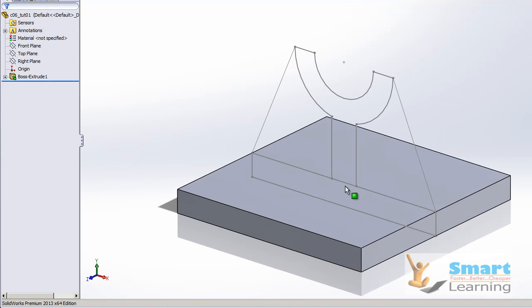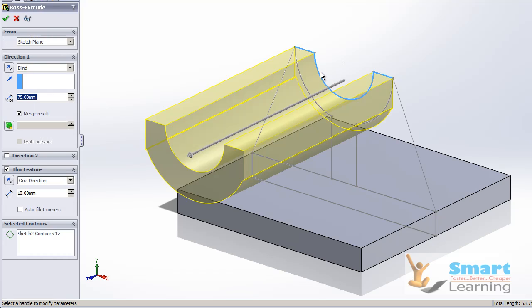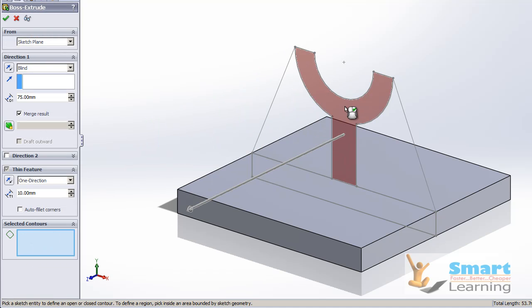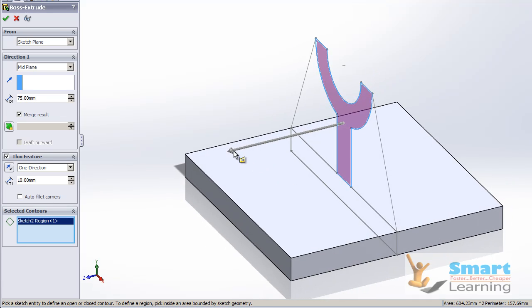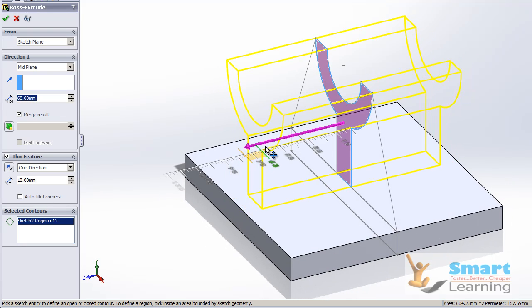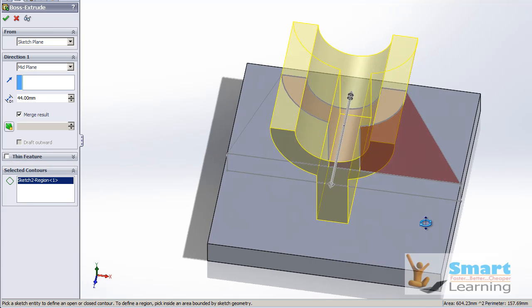Once you create this sketch, you have to create these particular features. You can find here that this is the contour sketch. I need to have this. So what about the control that I need from the mid plane? And you can directly control your depth here. Whatever depth you need to have, the thin feature, switch it off, as you can see.